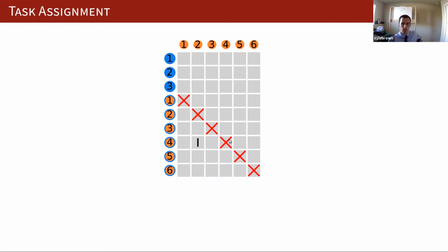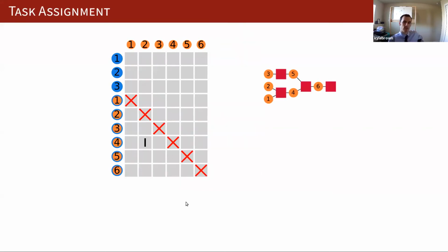So what if we put a 1 here? We're assigning the robot that just delivered object 4 to deliver object 2 next. That seems pretty harmless, but if we look at our project specification, we recognize a problem. If we say that the robot that just delivered object 4 should now deliver object 2, we are then asking that robot to go back in time, which is an even worse thing to ask of any robot to do. So we want to save our poor robots from this kind of grief as well. So that is excluded from the list of legal assignments. Same thing goes for any task that is a predecessor of the task associated with the dummy robot. So we exclude all of these entries from our assignment matrix.